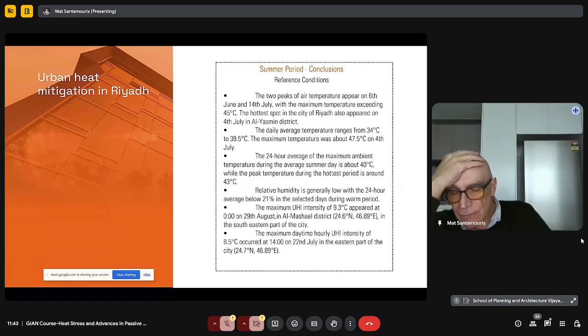By decreasing the surface temperature. How to decrease the surface temperature? By using materials which do not absorb heat, so they have much lower temperature. By using greenery, which presents much lower surface temperature, if it can be used. And how to increase the latent heat losses? By using more evaporative components at the city scale, which means more greenery or more water, etc.